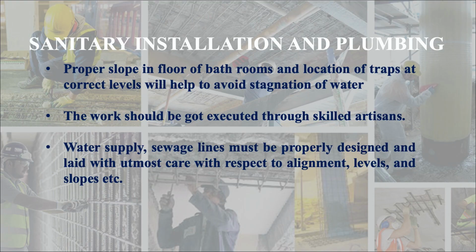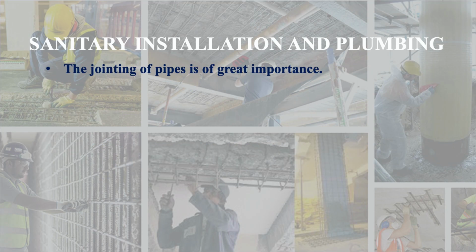Water supply and sewage lines must be properly designed and laid with utmost care with respect to alignment, level, slopes, etc. The jointing of pipe is of great importance, because if proper joints are not provided, then there will again be leakage, and as you know, leakage will cause the deterioration of the building.